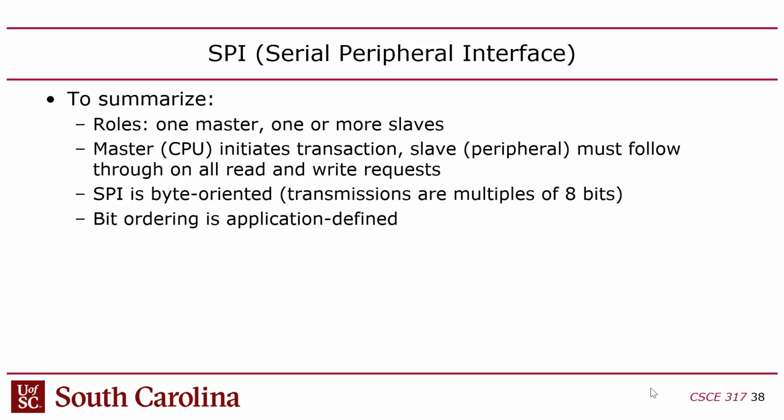But SPI isn't really designed for that, right? So generally speaking, you have just two sides. There's another protocol that we'll get into called I2C that's designed more for that. It's a multi-master bus where anyone can initiate, and you can have a lot of devices hung on a channel, whereas SPI is really just designed for point-to-point.